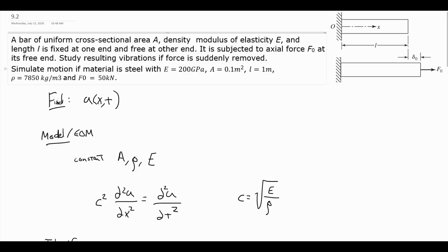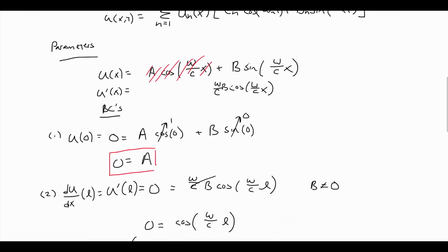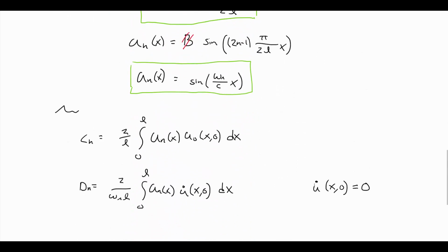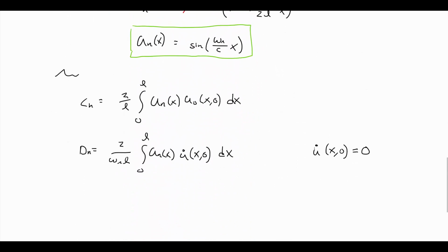Now in a beam, the amount of deformation is going to depend on how far away we are from that cantilever side. The end where L is going to deform more than when we get closer to the wall, until we're all the way at the wall and it's 0. So if we remember all the way back to strength of materials, we can figure out how much deformation we have. At the end of the bar, we'd use PL over EA.